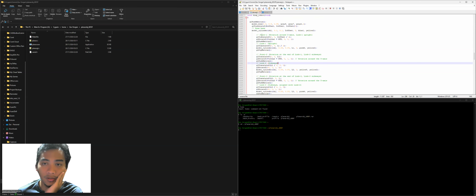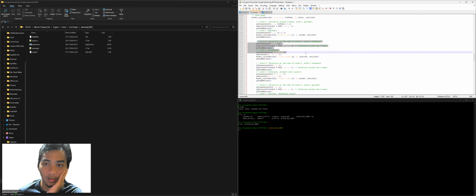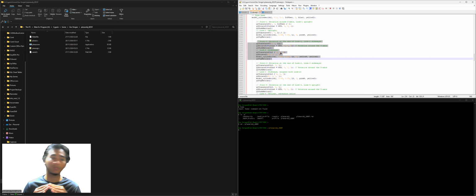First, the base is drawn like this. The next one is the joint, which will be rotated on the z-axis, XYZ, z-axis. The next one, joint 2, will be rotated on the y-axis, with the position translated like this, and every link will rotate or have a pivot point on the end of the other link, like so.